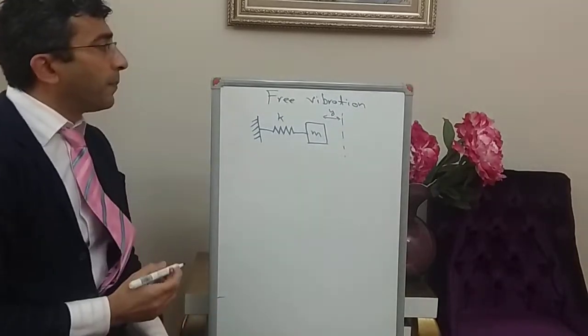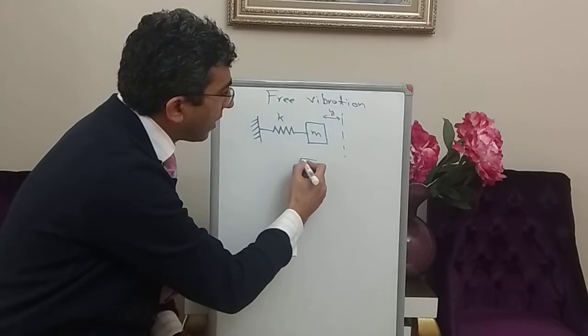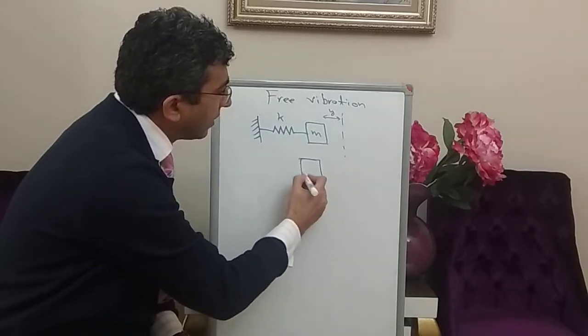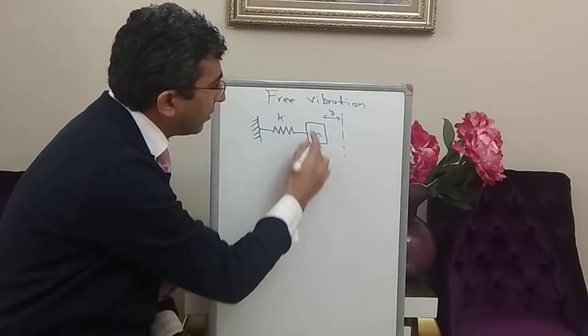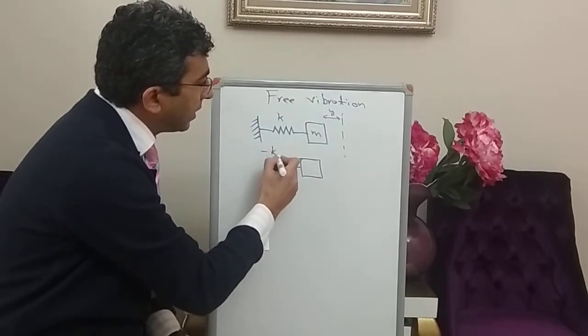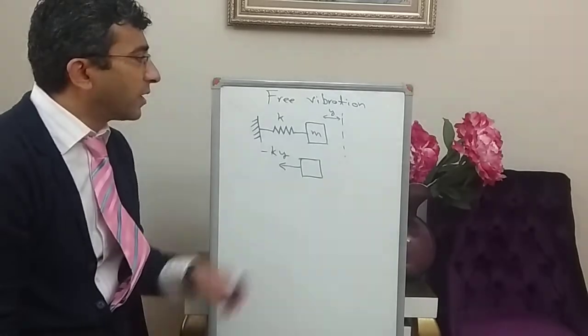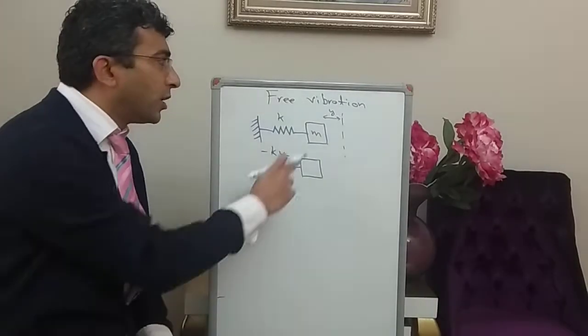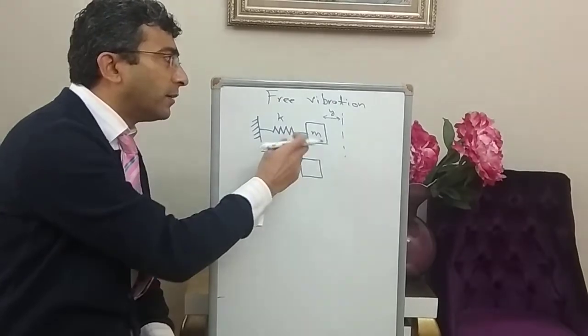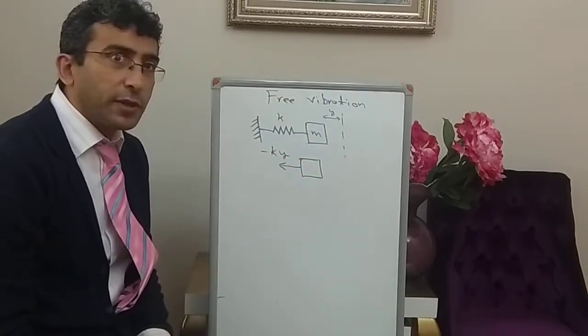Okay. So if you write the free body diagram for the mass, you pull it like that, it will go back, minus Ky. Okay, so there is only one restoring force. Actually, in reality, you should also have damping. One, we will speak about this now, after 5 minutes.